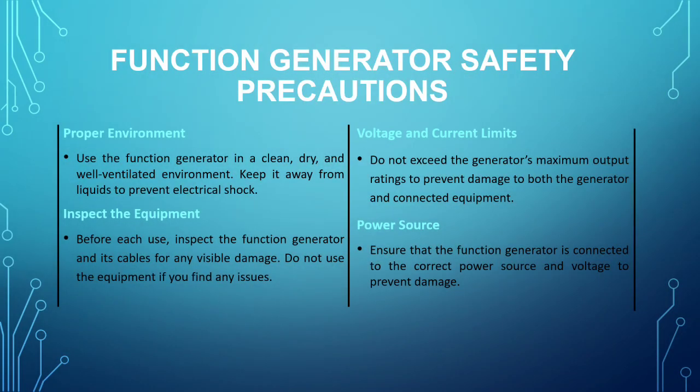Function generator safety precautions. First, proper environment. Use the function generator in a clean, dry, and well-ventilated environment. Keep it away from liquids to prevent electrical shock.